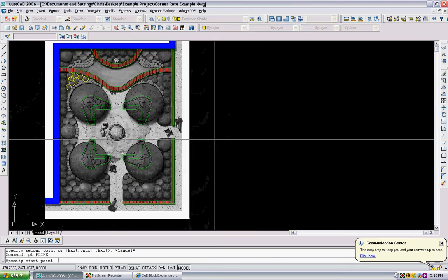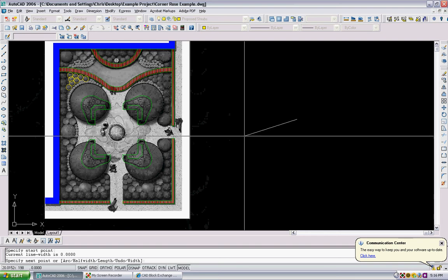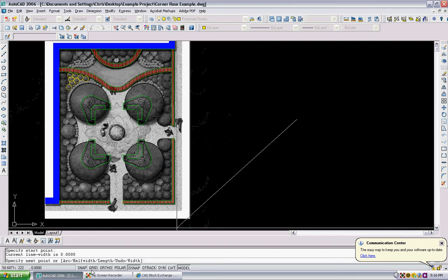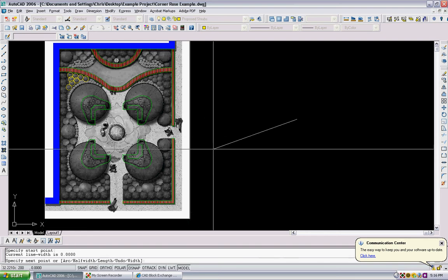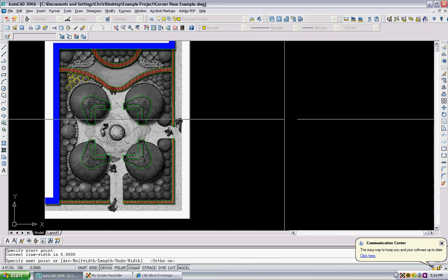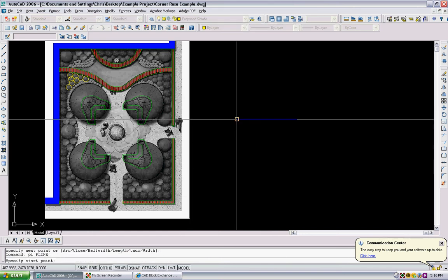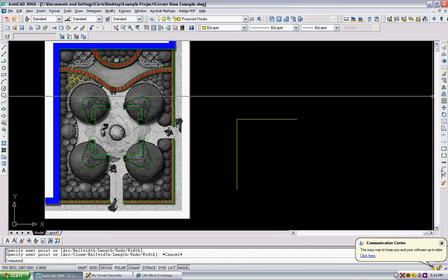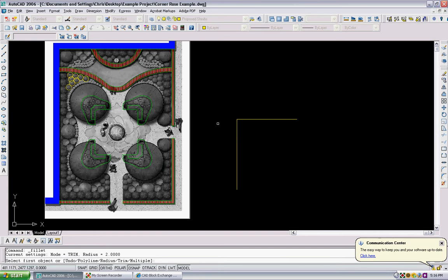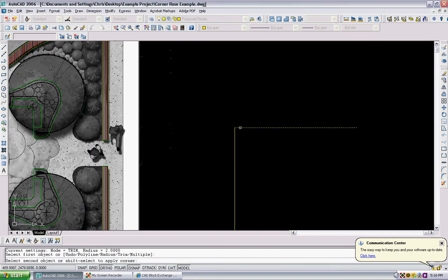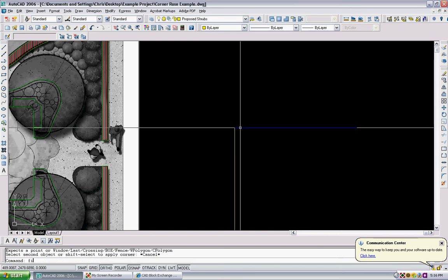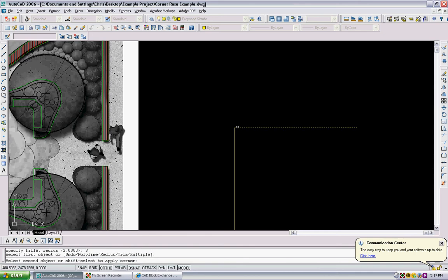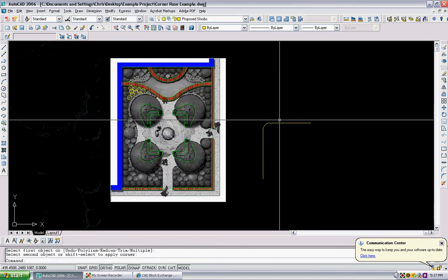But basically, what fillet does, if I have, it's my ortho on. Well, it was on. Draw a line here, and then I have another line coming off. And you can either click the icon here or just type it in. Well, type a radius first. Radius, I don't know, 3. Enter. Click on a line, it'll create that curve for you.